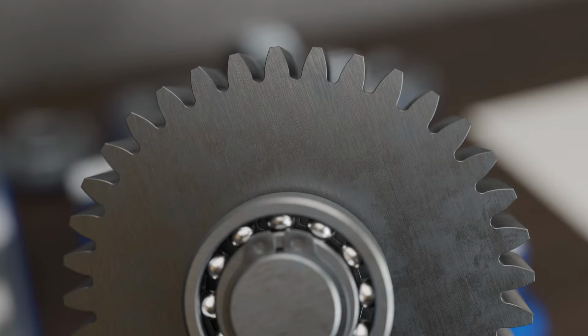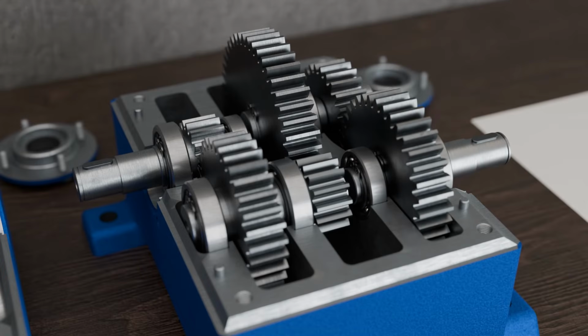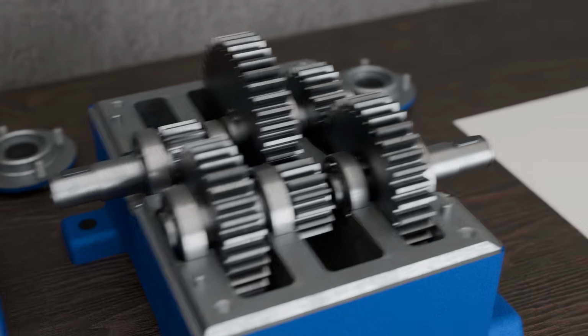The use of involute gears is due to the favorable meshing and the fact that they are relatively simple and therefore inexpensive to manufacture. To understand why the involute is particularly suitable for the tooth shape, you first need to understand how it is constructed. The construction of an involute, or more precisely the involute of a circle, is therefore explained in more detail in the following.